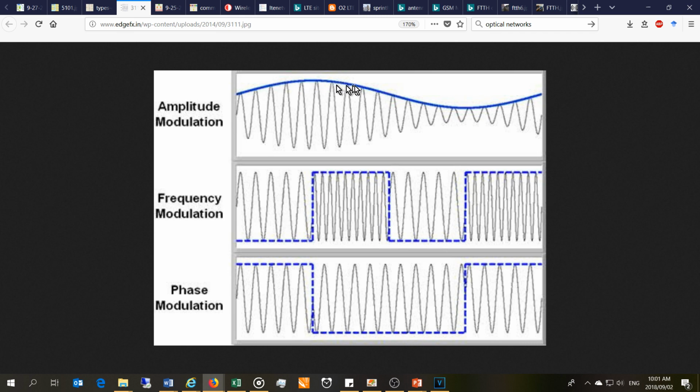I'm just showing you amplitude modulation. Can you see how the amplitude determines the intelligence? While here the amplitude stays the same in an FM wave, but the frequency represents the binary data. Can you see how the frequency increases here, maybe representing a 1, a binary 1, and when it goes back to the regular carrier frequency, it represents a 0. So we can encode binary information by representing it as frequencies. There we go. Higher frequency is a 1, lower frequency is a 0.